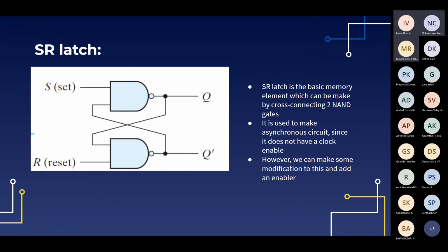It's a very basic memory element. It is made by cross connecting two NAND gates. We mainly use SR latch in making asynchronous circuits, which we are not going to discuss in this session. As you can clearly see, there is no enable, like the clock input, to this.